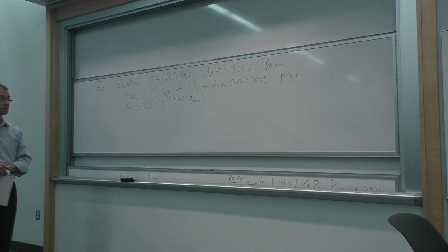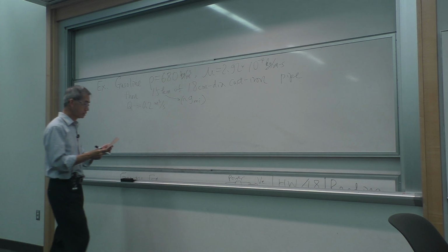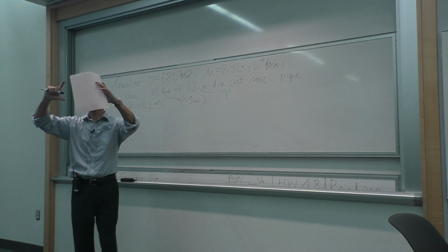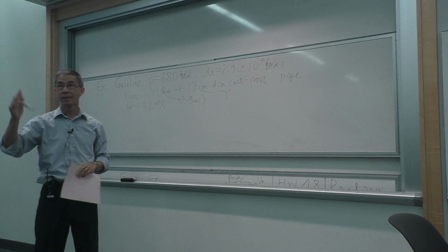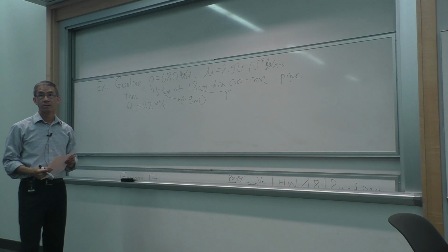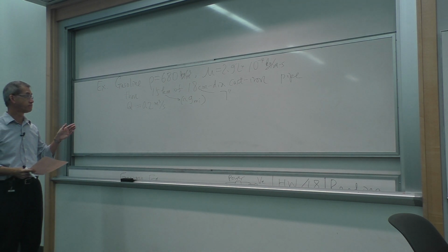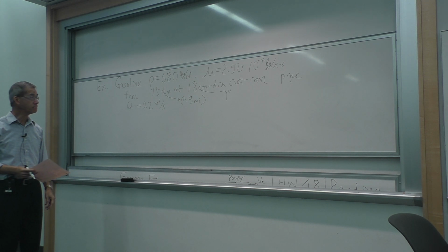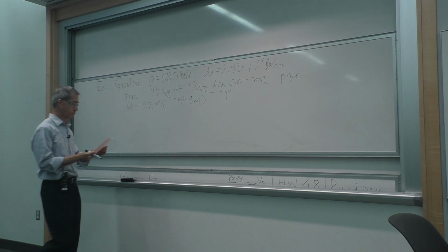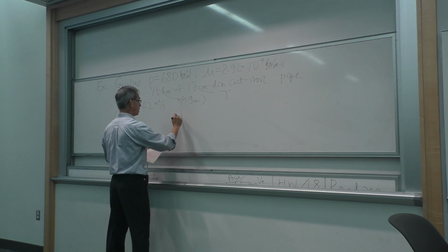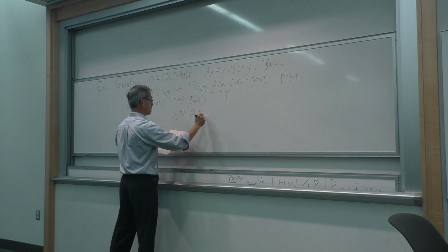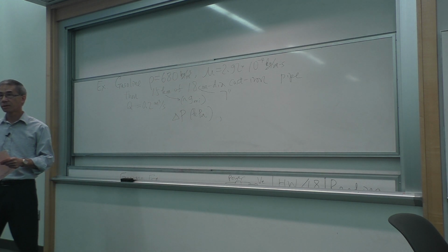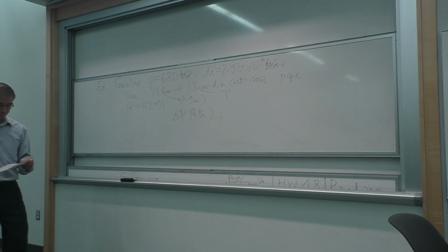It's pretty long distance. I mean, 18 centimeter, it's about 7 inches. A real tactical pipe about this size. You see it in photos in Alaska and so forth. So I want to pump gasoline at a little less than 10 meters per second over 9 miles. And I want to know how much pressure drop in kilopascal or atmosphere.